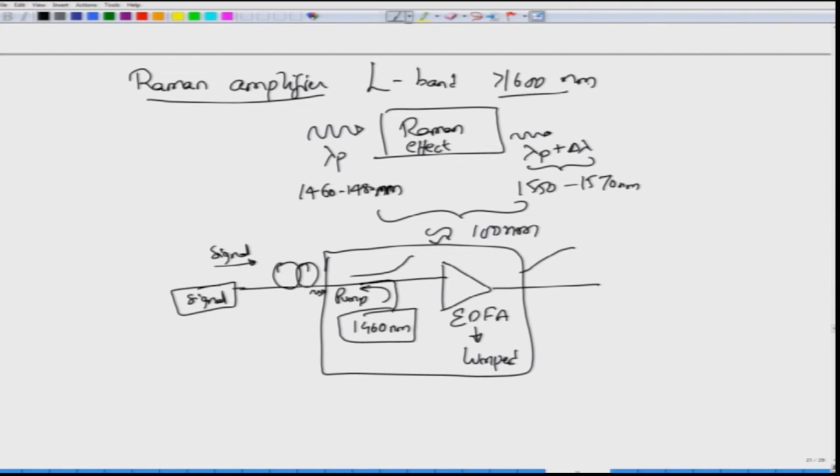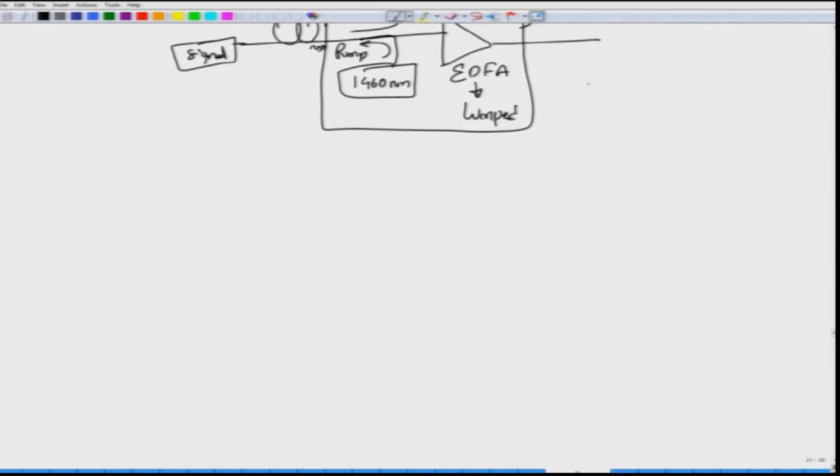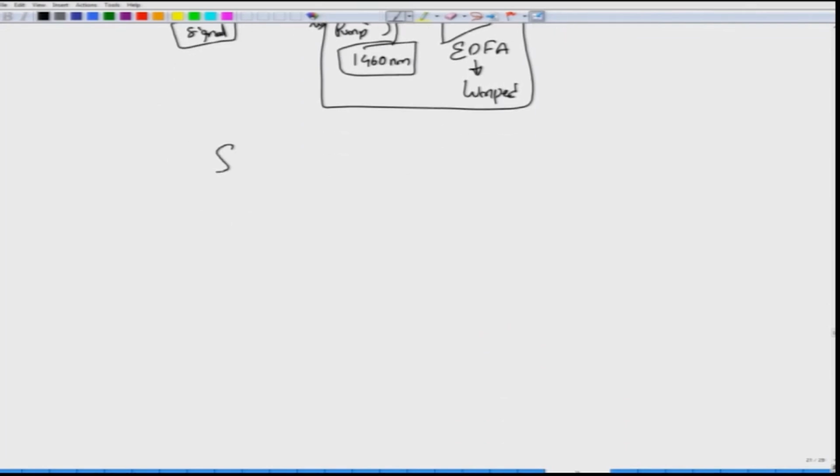In addition to this there are semiconductor optical amplifiers. I am not going to cover them in detail except to mention a couple of drawbacks. The gain is polarization dependent. Semiconductor optical amplifiers have a very high amount of crosstalk between the wavelengths. However, this high crosstalk is actually quite useful, as you can use it as a wavelength converter to convert from one wavelength to another. And these days, SOA based optical logic converters or header recognition units are being implemented.